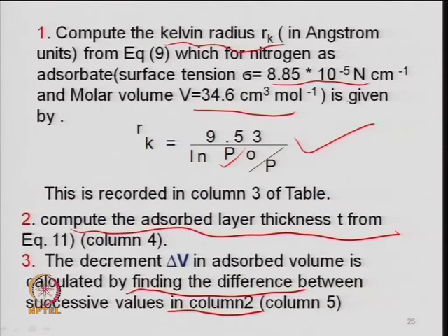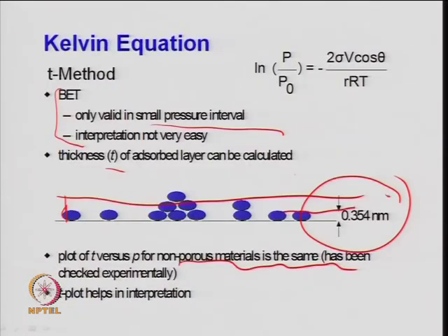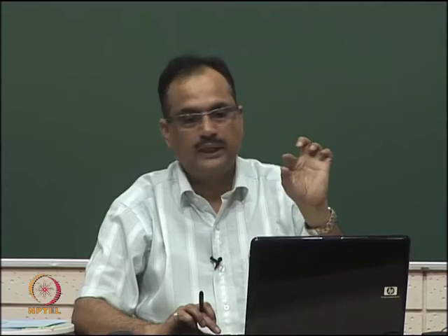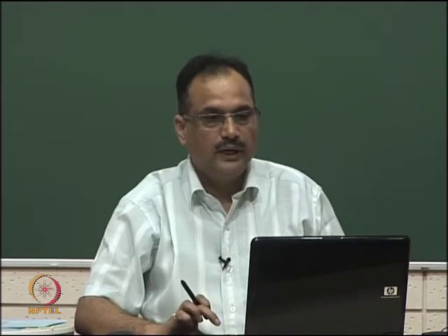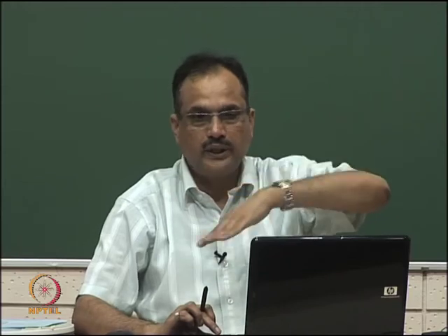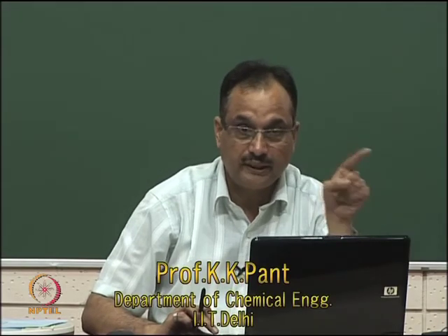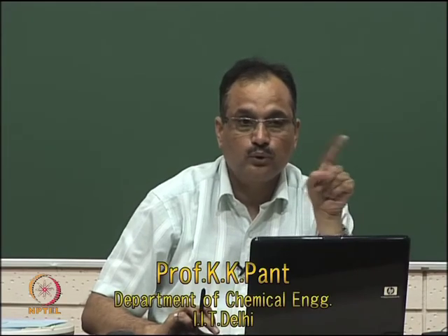That is basically the number I was talking about, and it can also be calculated for a non-porous material. The basic idea is to calculate the mass of the nitrogen molecule which adsorbs, and the thickness of that layer, the height of one monolayer. That is nothing but calculating with 16.2 angstrom square as the area covered by one molecule of nitrogen. In that, the mass of the molecule is m by n0 rho, right. That is what I calculated earlier, r is equal to (m by n0 rho) to the power 2 by 3, the radius of the nitrogen molecule. So, that is related to this.